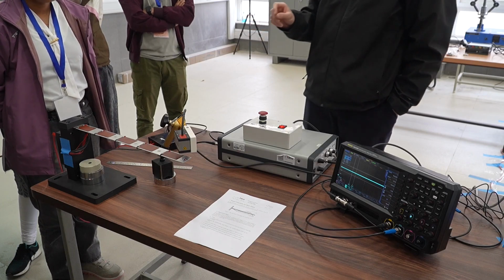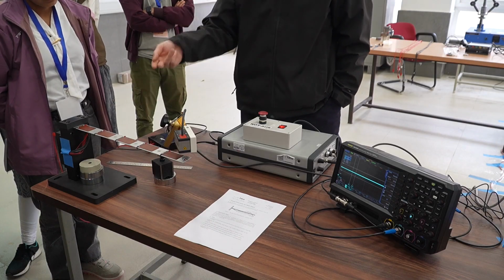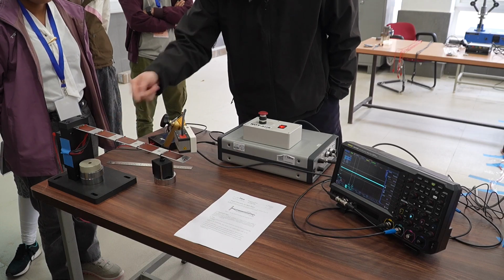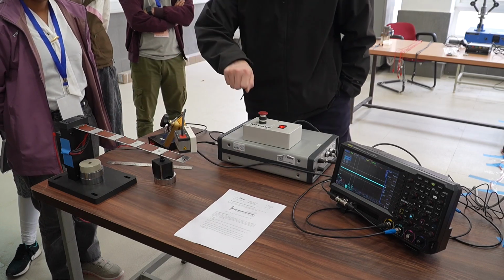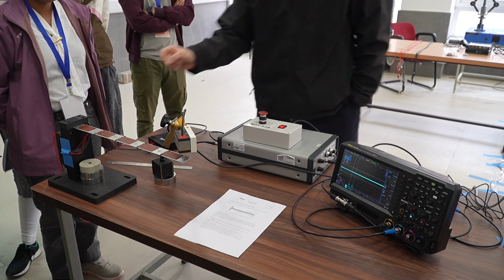And now, if we, for example, have the laser here and we go to the first and the second eigenfrequency, then we can measure the amplitude here. And then we shift the laser to here, go to the first and then to the second eigenfrequency, and then measure the amplitude here, then here and here.